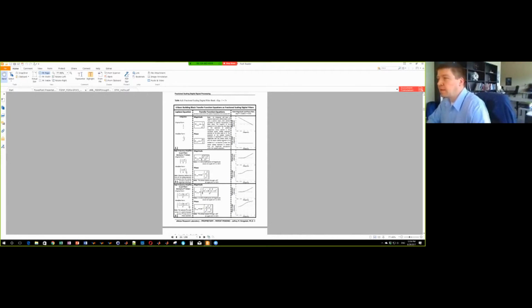If you take any time series or signal in the time domain, transfer it into the complex frequency domain using the fast Fourier transform, and then look at the spectrum and fit that with a linear least squares fit slope, you will find a scaling exponent, and that scaling exponent is representative of the active integration or differentiation of a signal. So, for example, if the scaling exponent is 2, that's an integration being performed on the signal. If the scaling exponent is -2, that's a differentiation being performed on the signal.